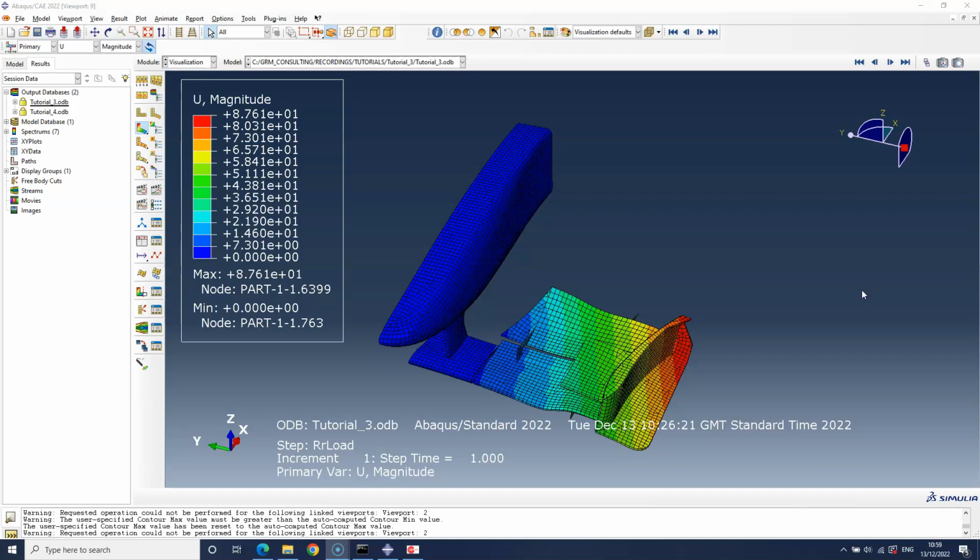This is tutorial 3, the ply shape optimization of a front wing using an advanced response. This tutorial aims to use multiple methods, one of them being the ability to define multiple ply pattern sets, each one having its own different coordinate system. Another is using laminate thickness constraints with predefined element sets. And another would be the ability to define an equation-based function, considering multiple displacement responses.